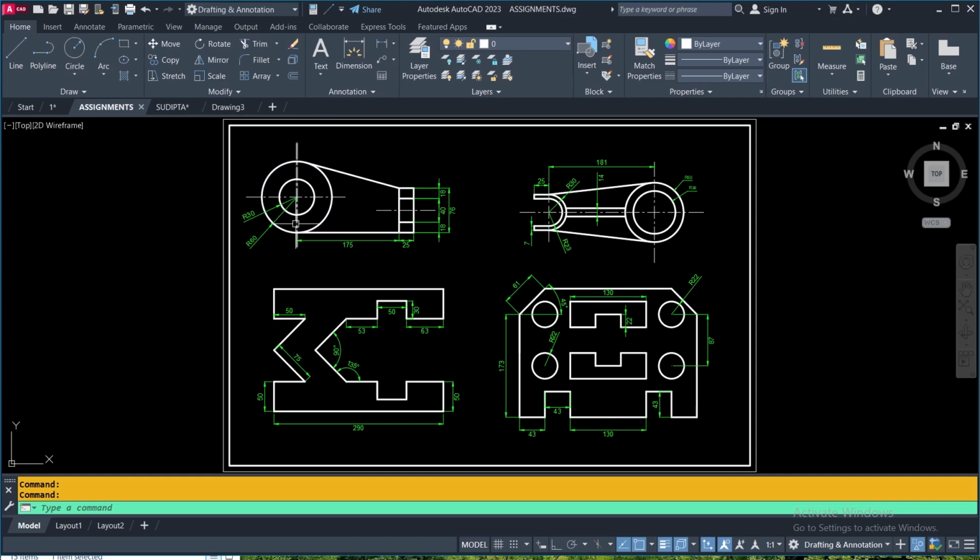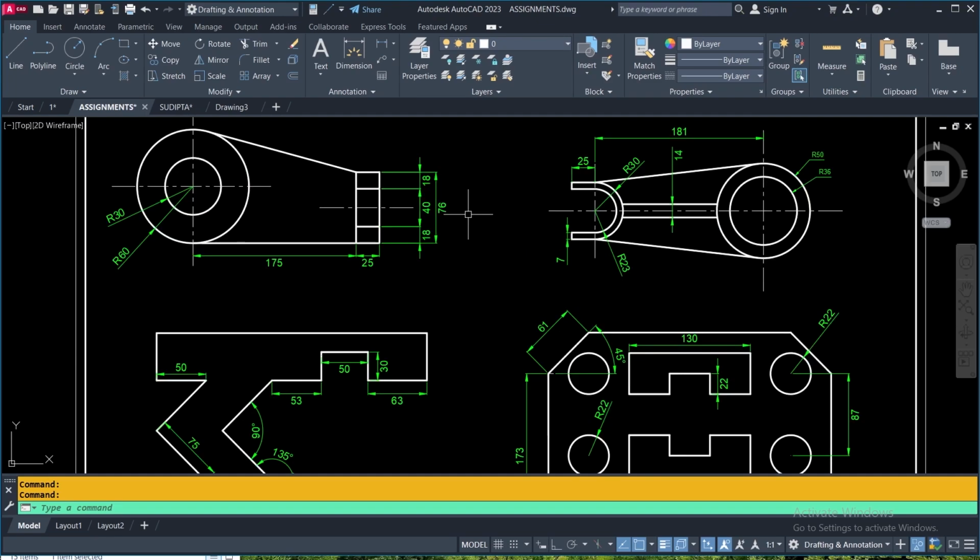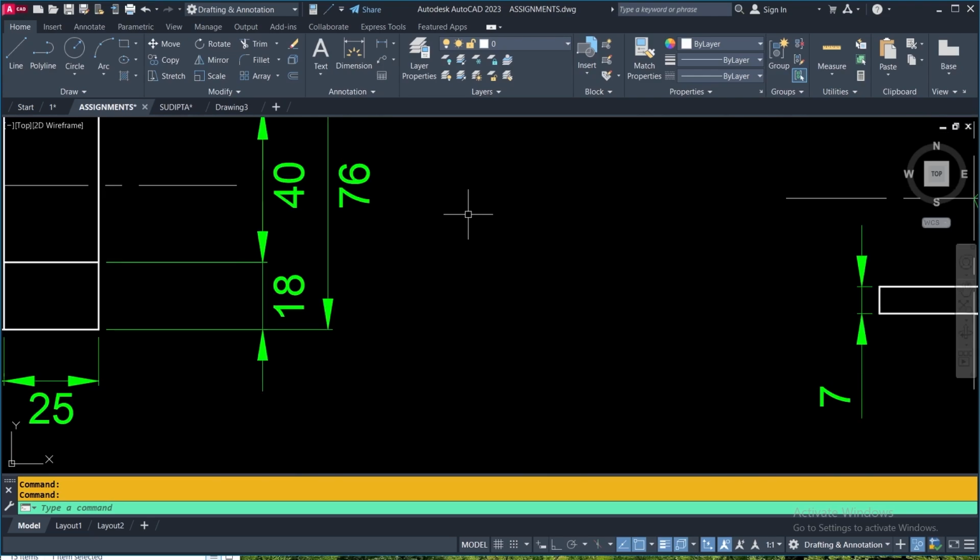Suppose in this figure 1, I want to draw something inside this smaller circle. Then I have to zoom in, but before zooming in, I will move it to the center of our drawing area, because you see, if I zoom in from anywhere, that is rotating my scroll wheel upward, it is going away.